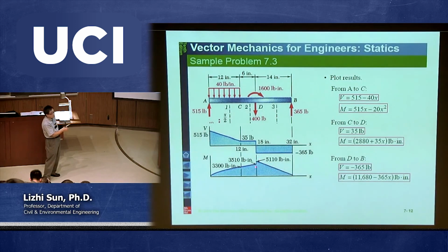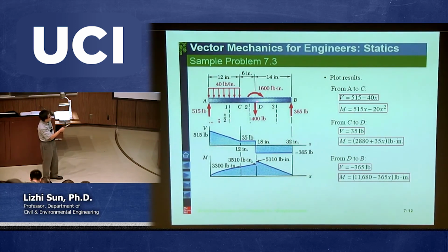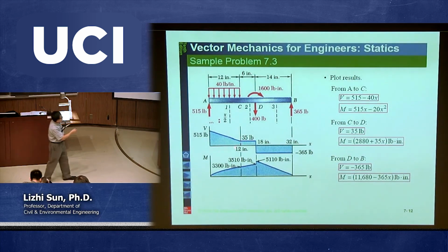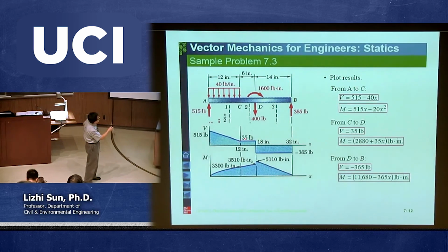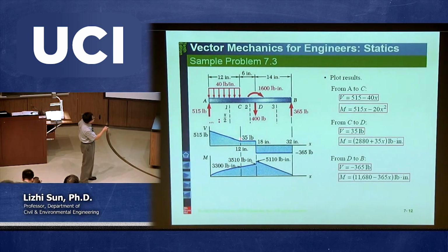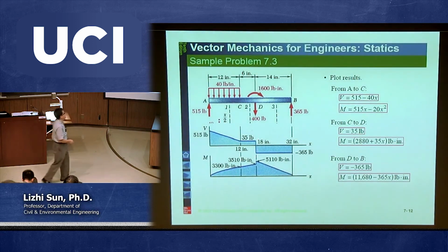And the reason we have a jump, I told you last time, is because of this applied moment there, okay? And the reason we have this force jump is because there's a real force here. The reason here there's no jump, there's no discontinuity, okay? It's continuous here. We do not call this a discontinuity. There's no jump. It's because all of a sudden it stops, but actually it's slowly stopping. That's why the slopes are different, but this is still continuous. But this is the real jump.